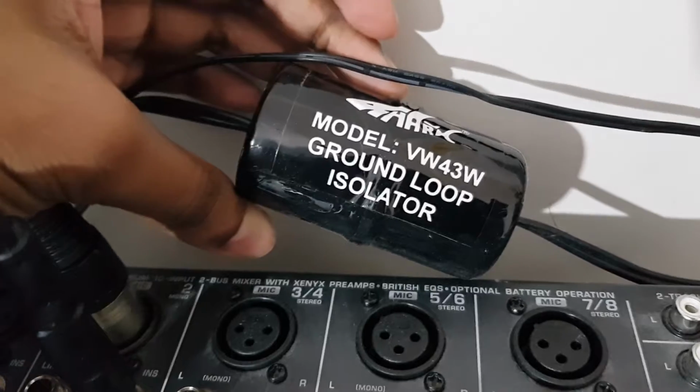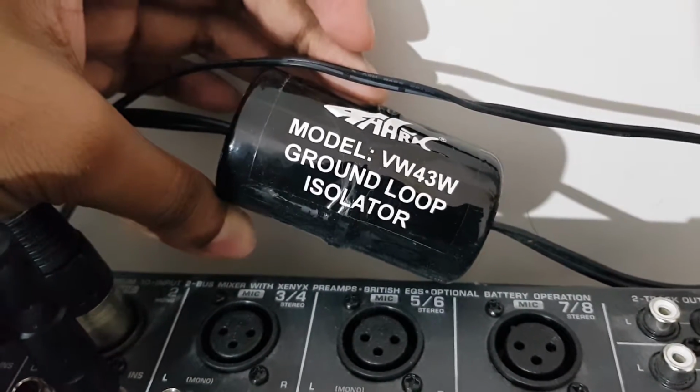But before I actually do that, I have another thing that I use. You could just connect the RCA cable into your audio interface from your mixer. Basically, you can do that, or you can take it another step further to reduce hum and interference. I use a little device called a ground loop isolator. Inside this little thing is a conductor which reduces the interference. It grounds the signal better.